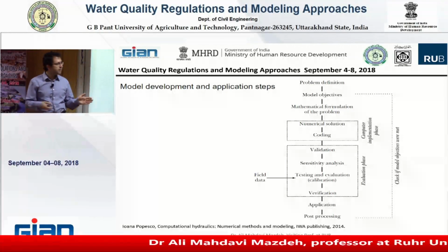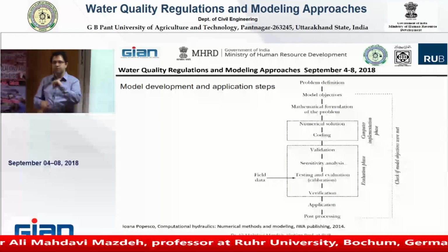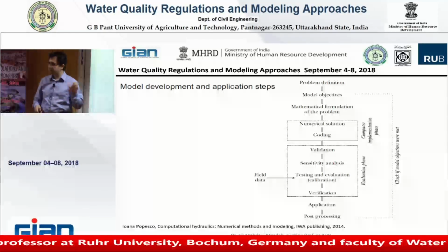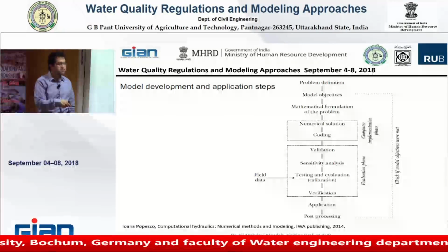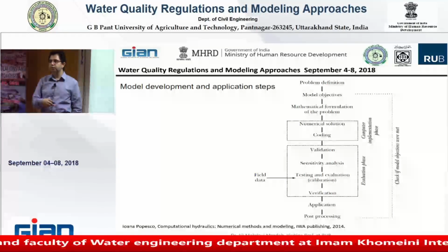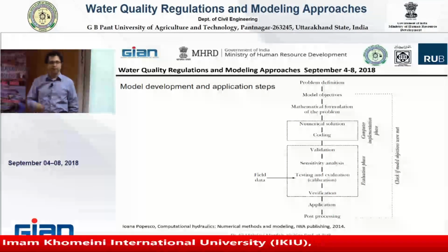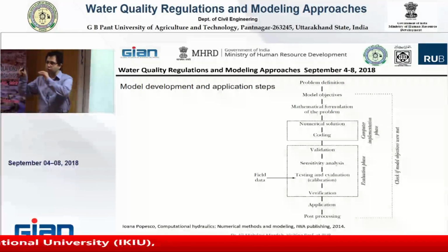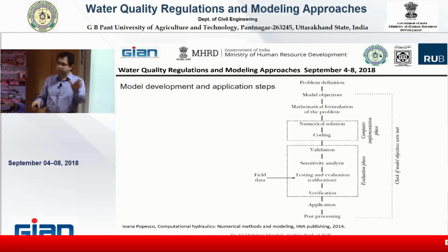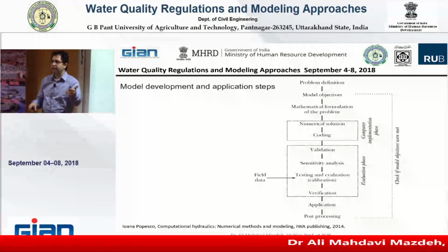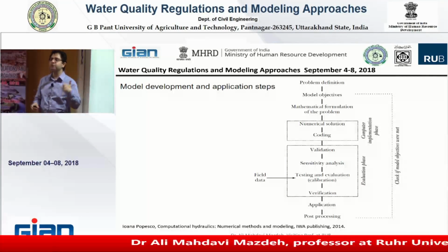So if you have 10 water depths and 10 discharges and calibrate this formula, and you bring C equal to 0.7, then of course this formula gives a good result for this data. Yes, if you test them again, they are good. But you must test with new data.